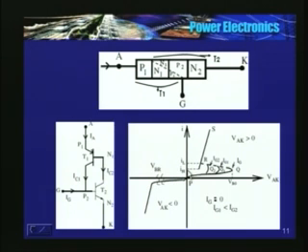So to turn off the device, I will repeat, the current flowing through the device should fall to a value less than the holding current. How does it happen? We will see whether it happens naturally or do we need to do something different to reduce this current. Okay. We will study it during the appropriate time, not now. So that is about the SCR characteristics.